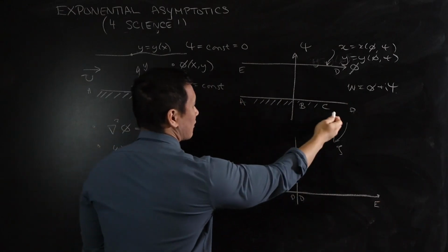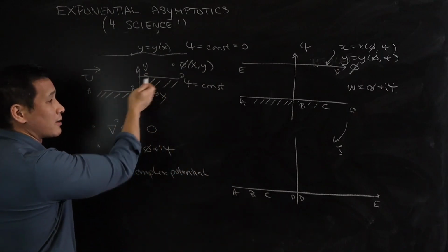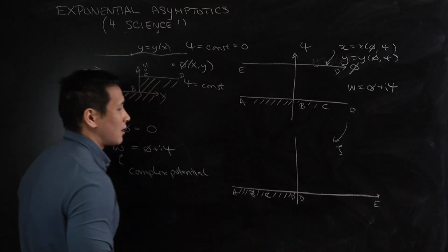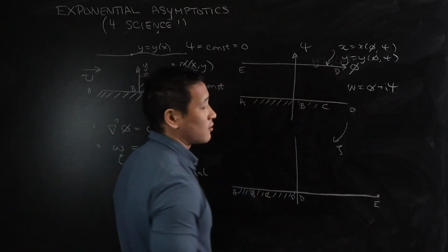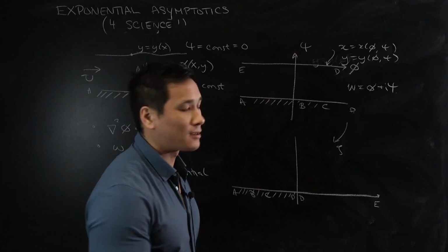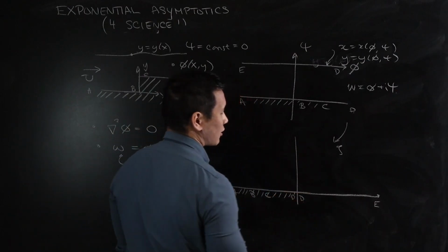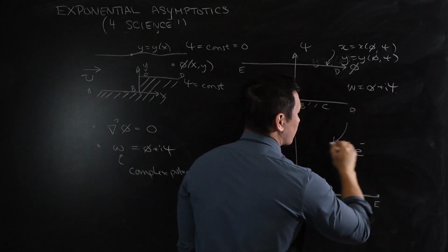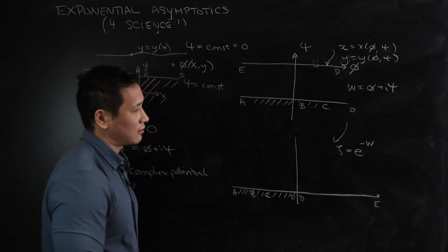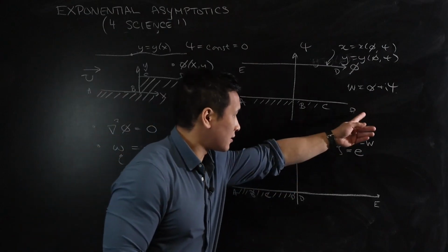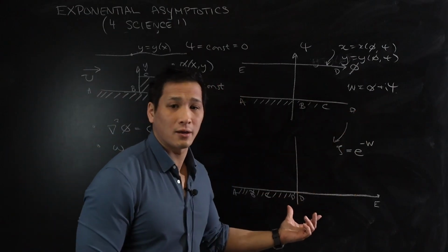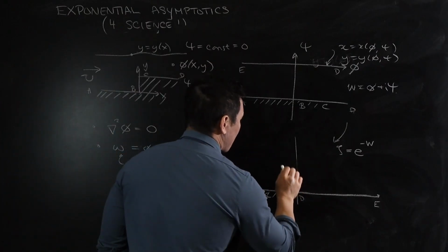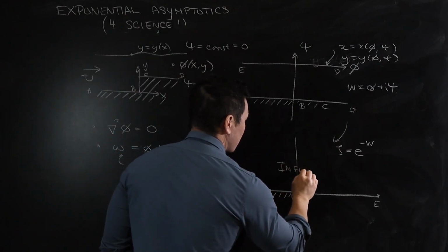So that the solid boundary, which corresponds to the bottom topography, has been mapped to the left half axis, and then the free surface, the thing that you're largely concerned about trying to get, is now along the positive real axis. Okay? And I can do this with a coordinate transformation that just simply looks like that. So if I just send the points W to the point zeta in this way, I have that. And then now this upper half plane is the in-fluid region.